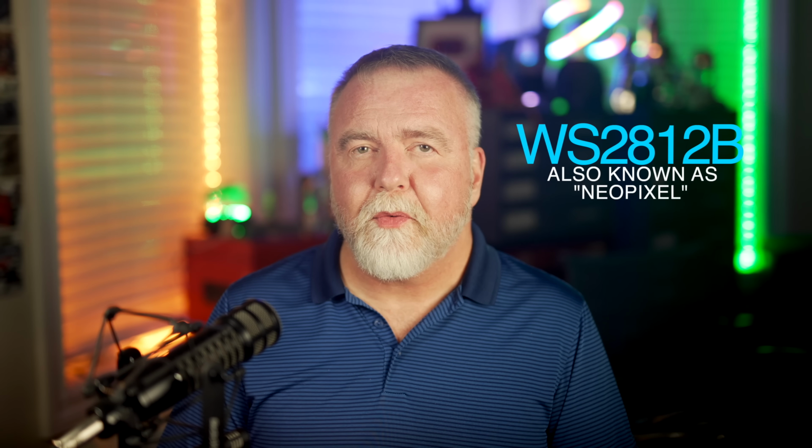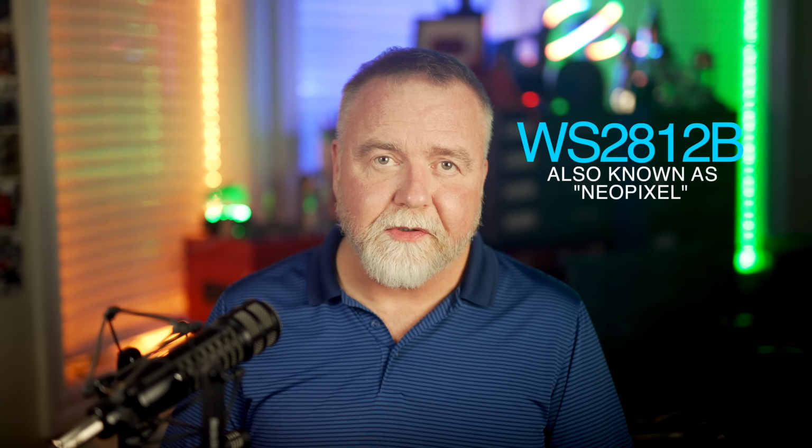Let's take a look at the parts we're going to use today. The first thing we need, of course, is an individually addressable strip. What you're looking for is something compatible with the WS2812B standard and running at 5 volts, ideally.